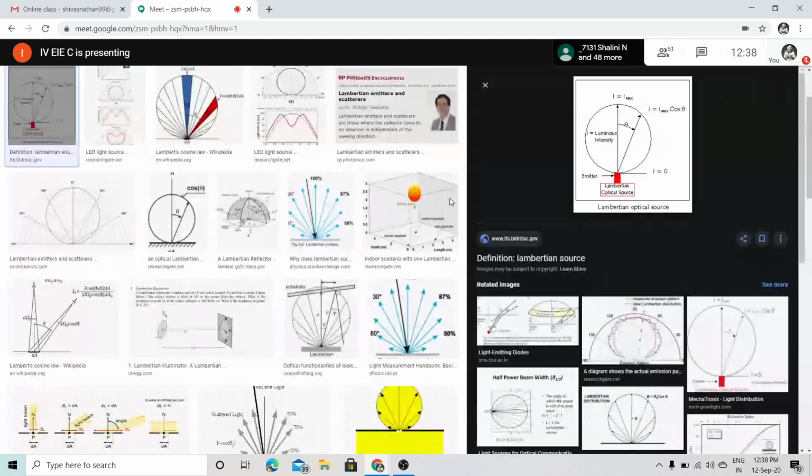We are going into the techniques where the measurement of length is done using an interferometric method. What you see here is a diagram which depends upon the same principle of interferometry. So you will find a beam splitter. Whenever we speak about interferometric methods, you will find a beam splitter there.